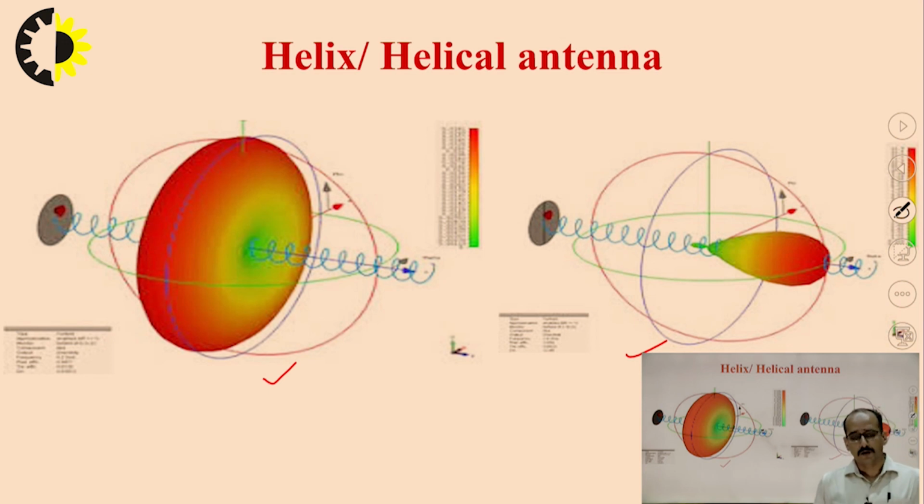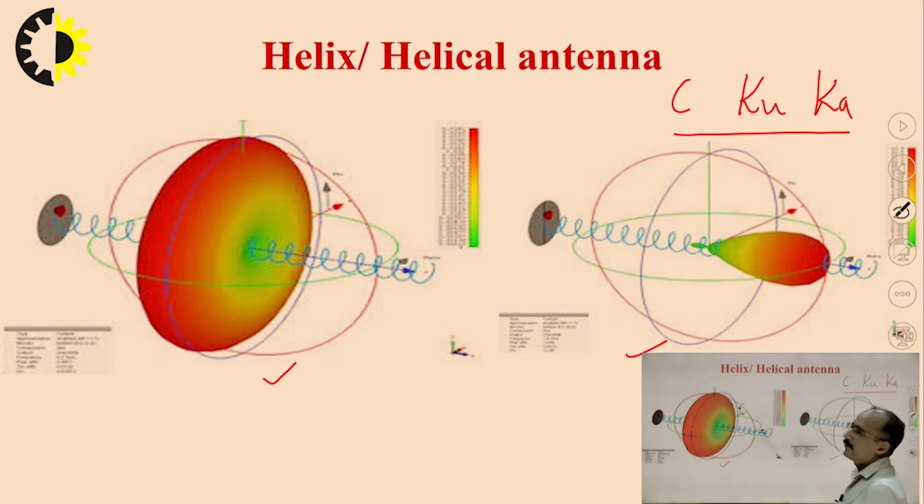So when we are talking about satellite antennas combined, you can easily identify one point: mainly the bands are Ku, C, and Ka, and for these bands we have wire antennas, parabolic reflector antennas, horn antennas, and antenna arrays or phased array antennas to create the beam, all as per the requirement. So this is all about the antenna subsystem part of a satellite. In the next lecture, we will discuss the heart of a satellite subsystem, the communication subsystem, which is called the transponder. So till the next lecture, thank you.